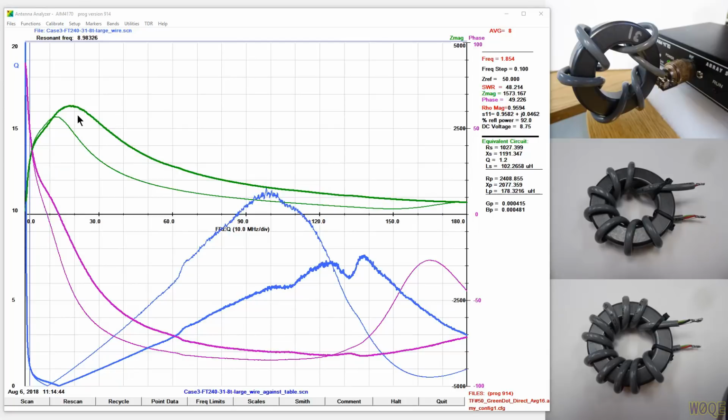And in this slide, we have shown in the wide trace the exact same curve we saw previously, which was the 8-turn winding. And we saw the impedance being slightly over 3,000 ohms at just a little bit below 20 megahertz. I took that same core and I moved the analyzer down onto the table, and I extended the wires about half an inch is all I had to extend them, and I laid this flat against the table. Laying it flat against the table reduced the impedance to this number right here. So we saw a reduction in frequency where it became capacitive, and we saw a peak reduction in the actual